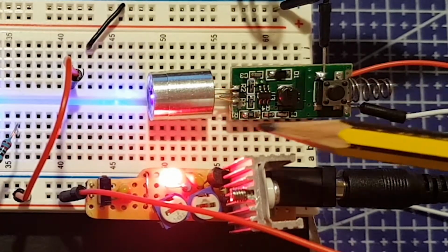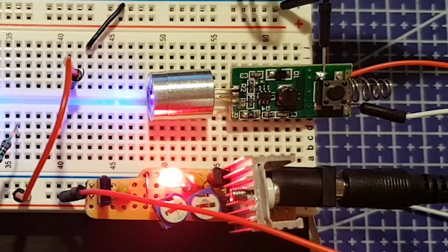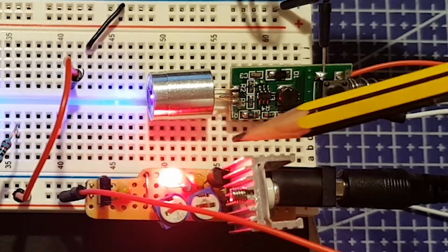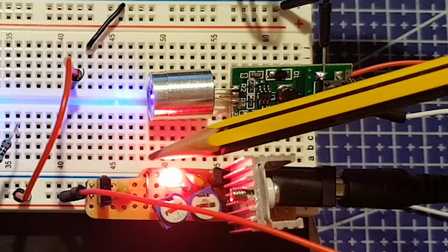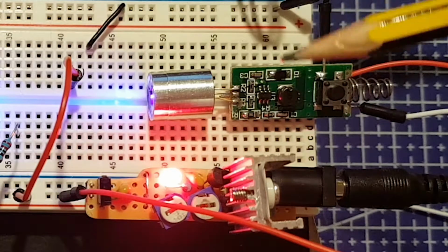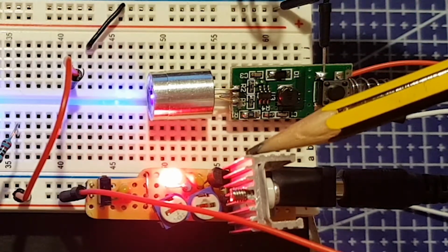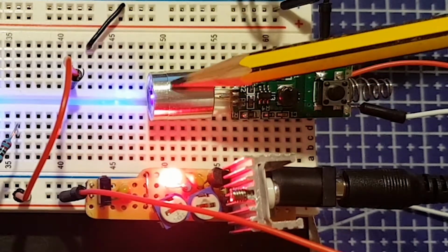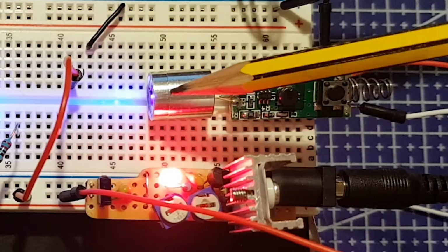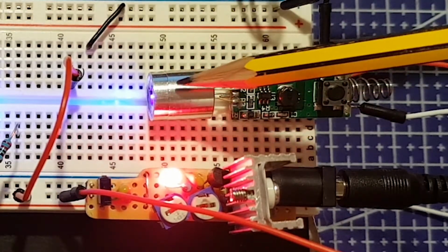And obviously if you didn't have this, you would have to build a current limiting driver circuit, which looks similar to this power supply here, but instead of supplying a constant voltage, would supply a constant current. More powerful lasers can get very hot, so we'll also need additional cooling on the diode itself and also the driver circuit. One of these heat sinks here is generally used on the driver circuit, as it is used in this voltage regulator here. And also you'd have a heat sink casing which encased the whole diode itself. The diode is actually a small part inside this casing here.